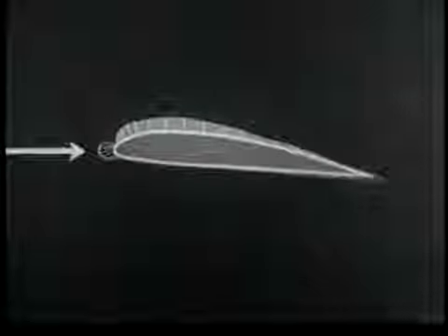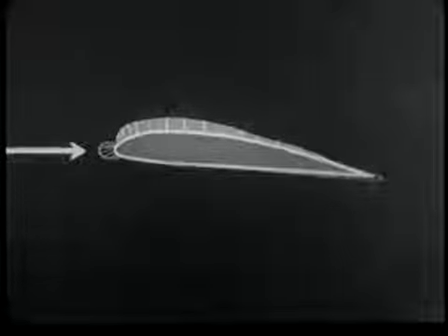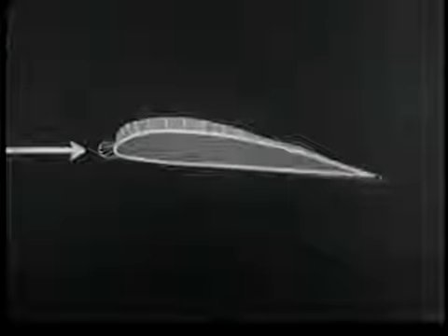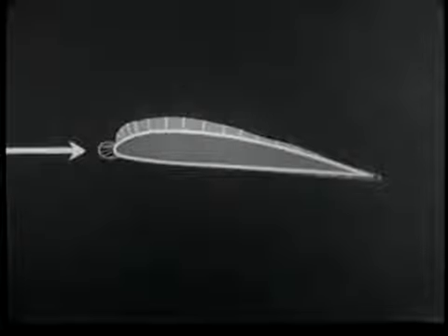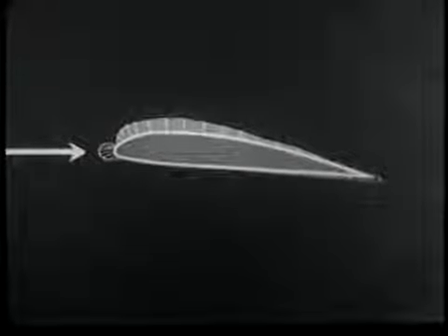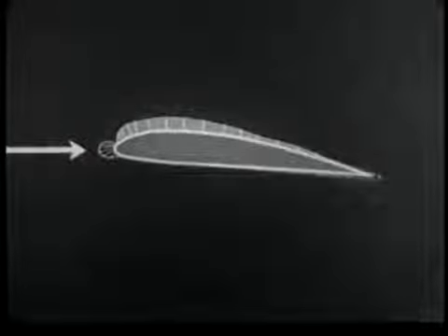As the angle of attack is increased, the positive pressure bulb moves lower down on the leading edge and back along the lower surface of the wing, enclosing the trailing edge. The negative pressure distribution remains fundamentally unchanged, although its values are greatly increased.